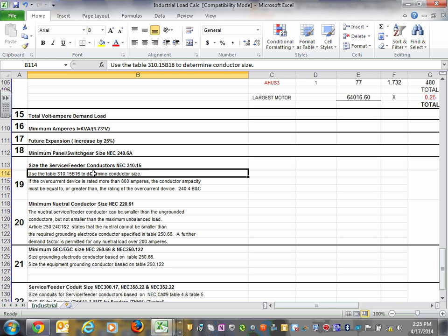When I teach the exam prep, people ask, which column am I going to deal with, Chad? In 310.15(B)(16), there are 3 columns: the 60-degree column, the 75-degree column, and the 90-degree column. When you deal with the panels and feeders, 3-phase, 99.9% you are dealing with 75-degree lugs. So you're almost going to go directly to 75 in size, unless you are derating, of course. But we don't group feeders, do we? Do you put a feeder for the receptacle panel and a feeder for the lighting panel together? Now we have 6 or 8 current-carrying conductors, go derate; we don't do that. Feeders, that's one conduit per feeder. And if we need to parallel, we parallel them in separate conduits.